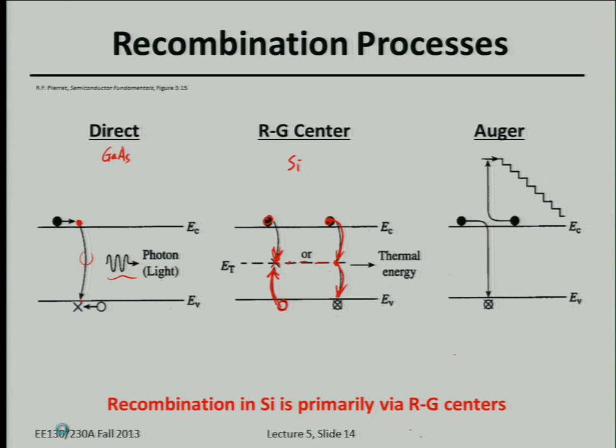This happens in the case of very high doping concentration. I'm just talking about electrons here, so we have a very high electron concentration. This is most likely to happen at very high N-type doping. That's always the case, because as you can see intuitively, you need a lot of surrounding electrons. That requires multiple particle interactions. Basically, that's the case for Auger recombination.